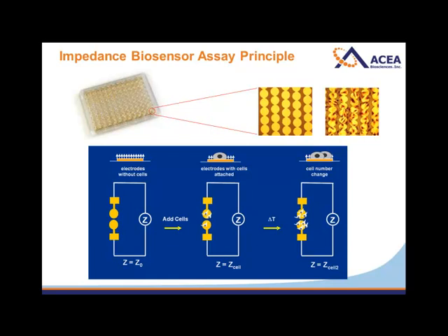The way the biosensor technology works is cartooned here. For simplicity, we've isolated two of these gold disc electrodes from the array, and you can think of this gap here as being the gap between the two rows. What the technology does is apply a very low electrical field across that gap. It's on the order of a 20 millivolt potential, much below the resting action potential of most cells. That allows us to essentially measure the current flow between these two open surface areas of the discs.